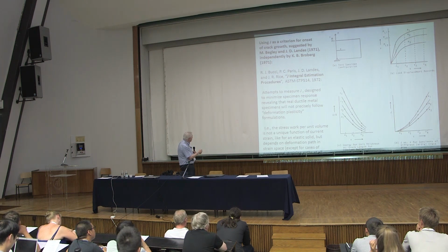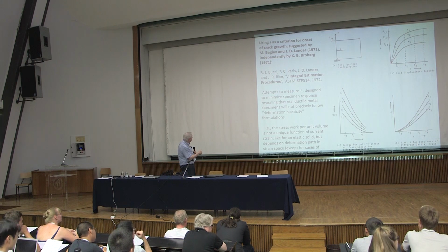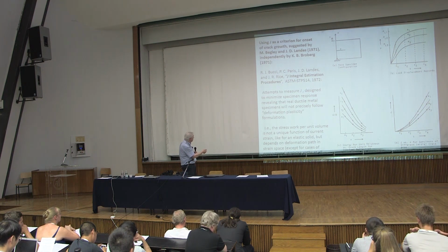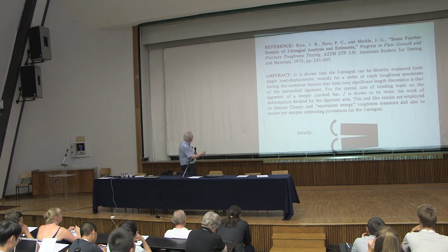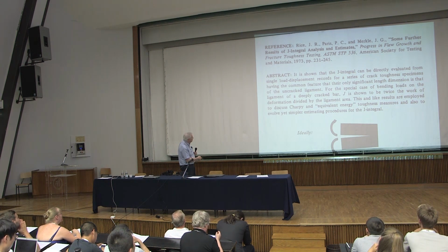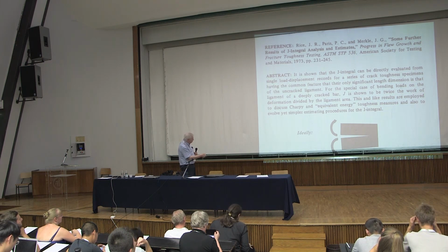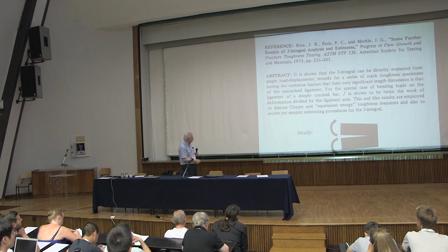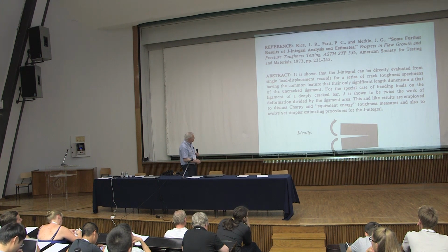A summary of some of that is in this paper. Well, I'm on that paper, but it was their idea to do this. I forget. Oh, and I think this was about simpler ways of estimating what might be learned from such experiments. Okay, and then a later paper showed how you could, if you had a very deeply cracked specimen, where the crack runs almost up to the end, and if it's loaded in bending like this, you can see how you can evaluate J from experimental measurements of the opening torque versus the amount of rotation of the ends. So those were kinds of applications.